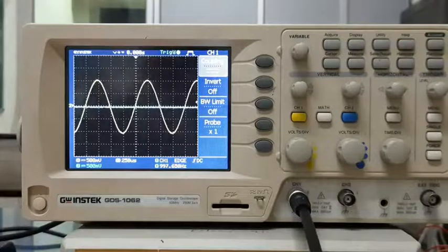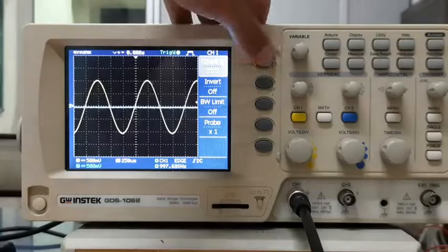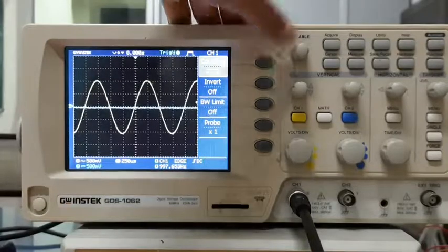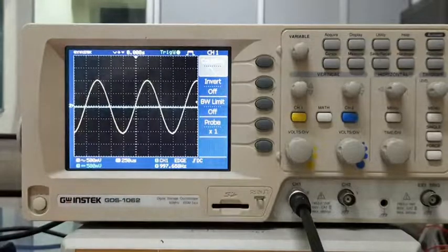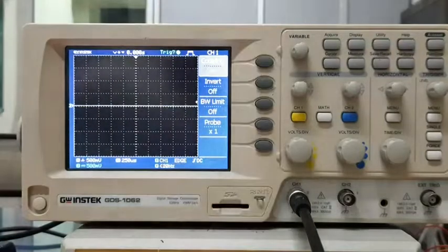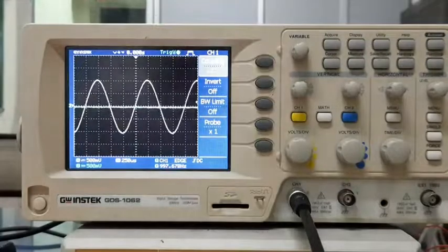So again, this kind of distortion that you saw just now, if you had noticed, is because of the instability in the cable, in the coaxial cable that was connected. If it's not properly fitted, if it's a loose fit and all that, then it might lead to this kind of instabilities, right? Okay. So just to go once more on the coupling. DC coupling, you will see the signal. AC coupling, in this case you will see the signal because it's an AC signal, so nothing changes. And ground coupling, you will not see anything, and then again we will switch back to DC coupling.